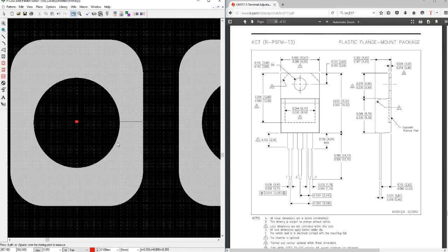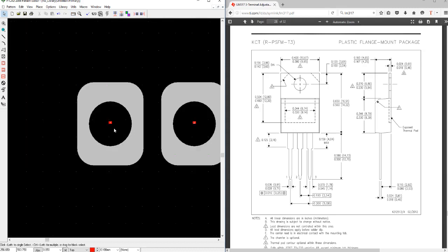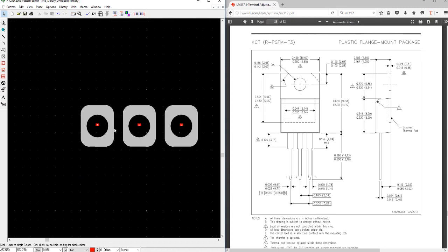So this 0.35 millimeters meets the requirements of most fabricators in the world. So let's stay with this pad. We don't want to reduce it further. We have a good distance between the pads to facilitate good soldering. We have met the annular requirement in terms of fabricating the board, so I think we are good to go on these pads. We've placed them on a 2.54mm grid.